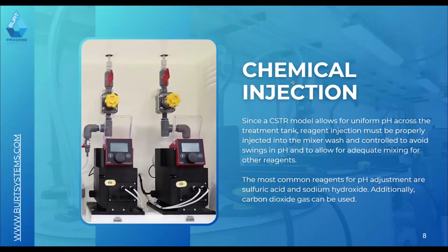And really, to comment, residence time is really nothing more than the tank volume divided by the flow rate. So when you're determining that, that really helps you determine your tank size. If you have a 100 GPM system at 30 minutes residence time, you need 3,000 gallons of volume, apologies, to maintain that 30-minute residence time.